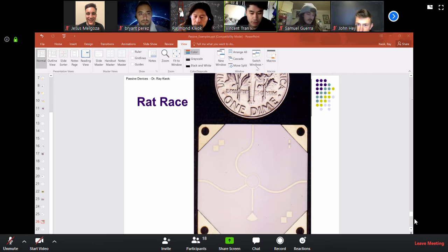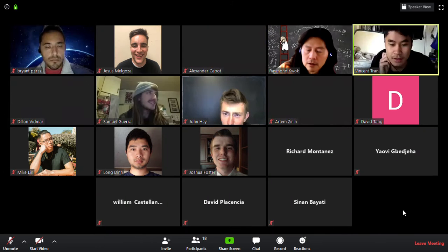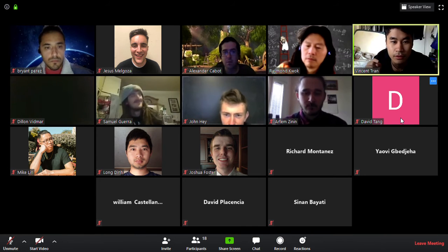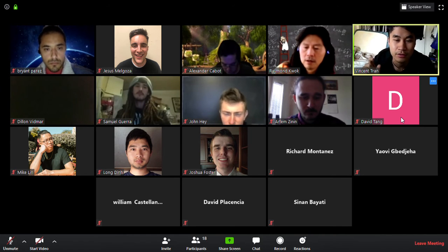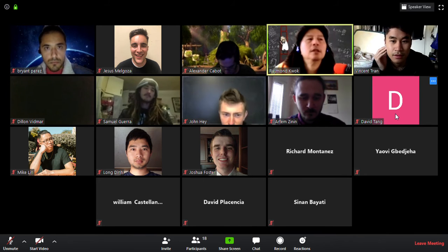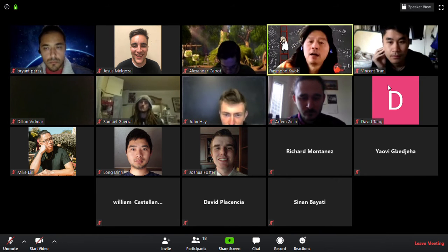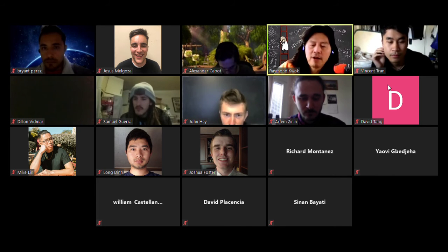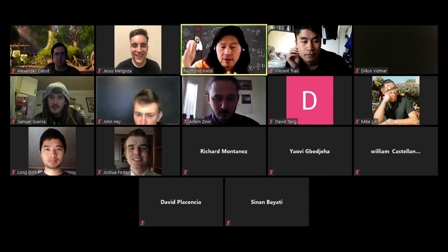I have a quick question. If we're doing the antenna array project, will we have to use a couple of these power dividers for splitting the power to each antenna, and then have a 90-degree phase difference divider for the circular polarization? Yes. You can do a Wilkinson power divider and then have a different line length to give you the 90-degree phase, right? Just another half inch or so of length.